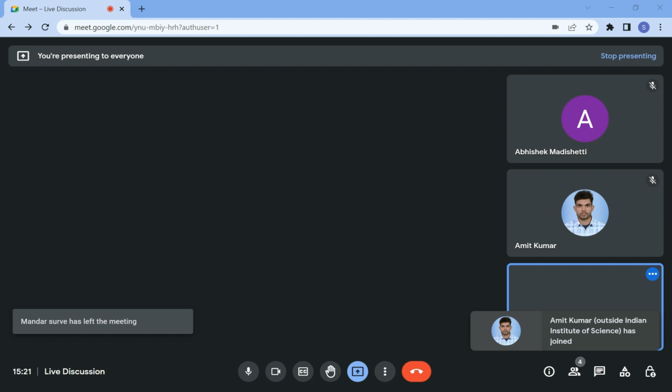So this height is L cos theta, and this length which is going to rotate here is the projection of the line when the line is inclined to the VP. So the length of this line is L cos, I'm sorry, this should be L sine, not cos.